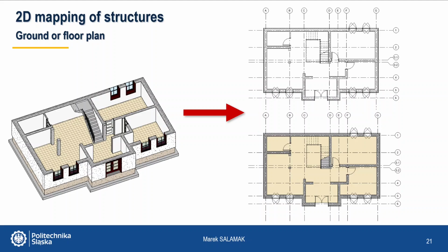They are a bit like maps that also have a top-down projection. But unlike a conventional map, a floor plan is usually a section formed by a horizontal plane roughly halfway between the floors. Objects below this level are visible, and objects on this level are shown as cut. Usually, we draw them with thicker lines or we use hatching. Objects above the cut plane are omitted or displayed as dashed.